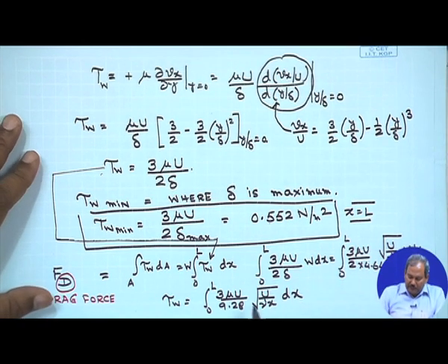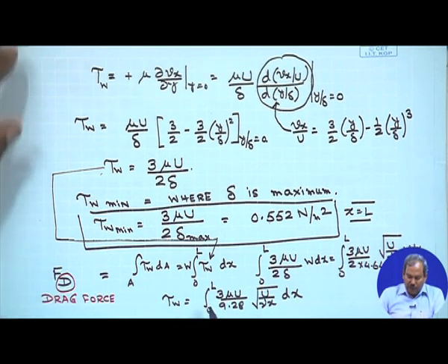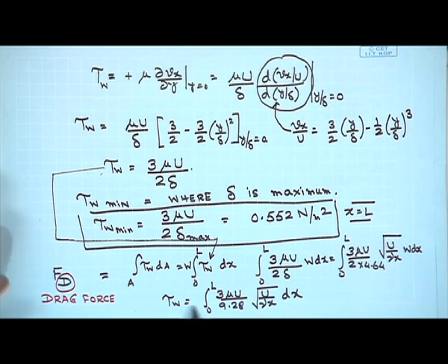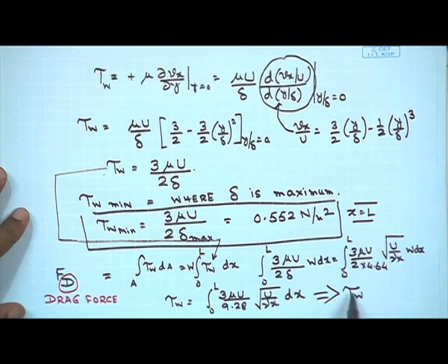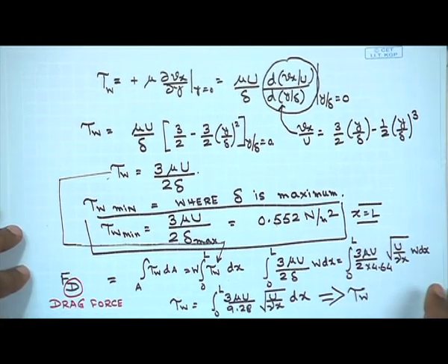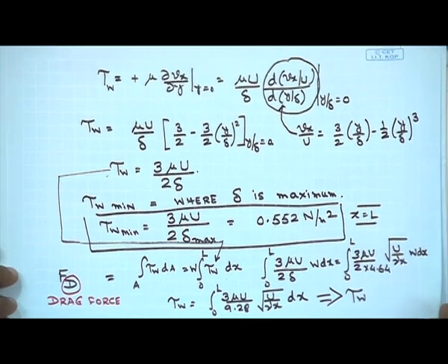So the rest is simple. You can simply do the integration over the entire length of the plate from 0 to L and obtain an expression for the force on the plate, and the final expression can be obtained from there, which I again leave it for you to find out. So this again underscores the advantage of using the momentum integral equation.